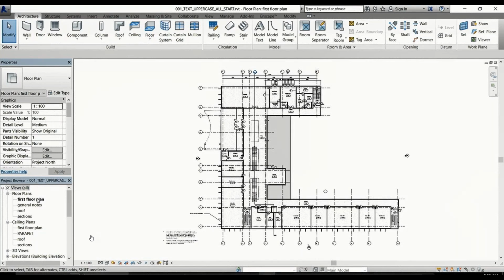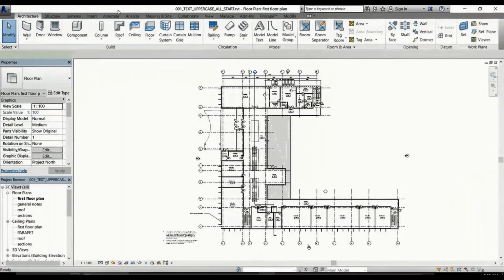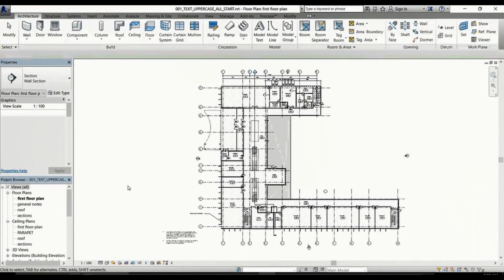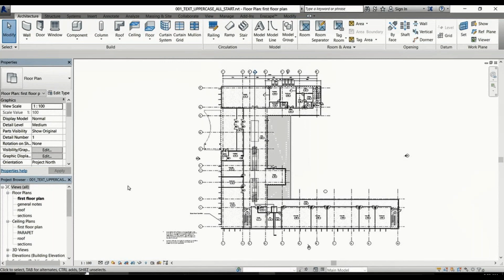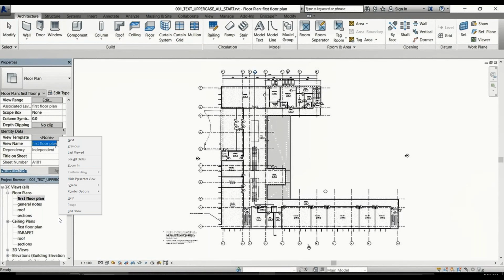Okay, so on the screen, I'm using our Revit demo, right? With the package that I'll share with you, you'll also be able to apply this on your project. Now, traditionally, to go in and change those view names, I'll show you in a minute, you'd have to go and click on the view. Right, so you click on the view and either right click on the view and change it, right? Or you go to the properties palette itself and retype it in there.